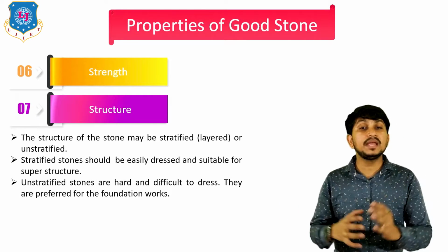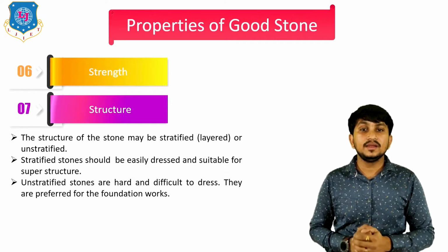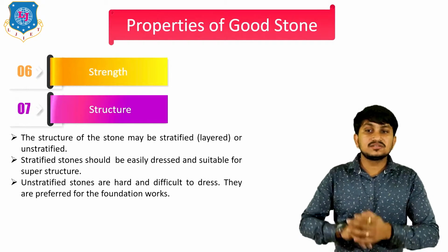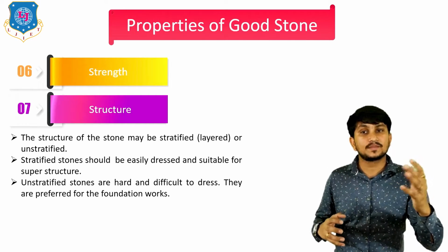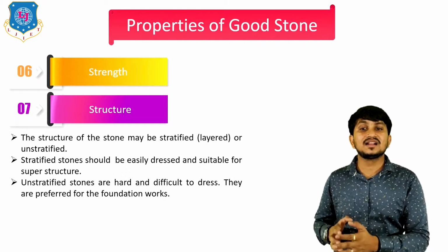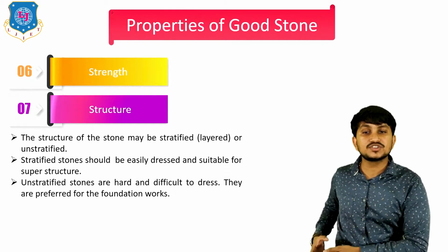Seventh is structure. The structure of the stone may be stratified, also called layered, or unstratified. Stratified stones should be easily dressed, suitable for superstructures. Unstratified stones are hard and difficult to dress. They are generally used for the foundation works.